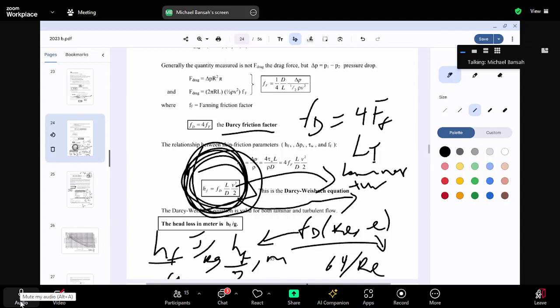The length of the pipe may be the total length. In your calculation, there is a pipe length, there is a pump. So at the suction line, there is a certain length. At the discharge line, there is a certain length. In the pump, remember the fluid covered a certain distance in the pump. That is usually represented in length equivalent, LE.